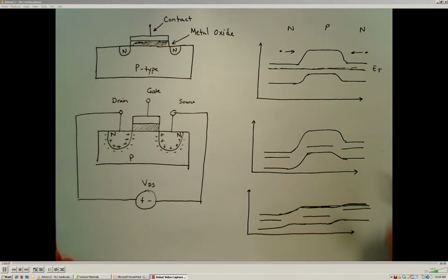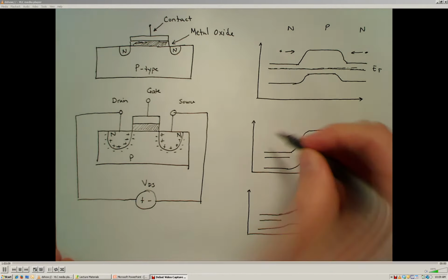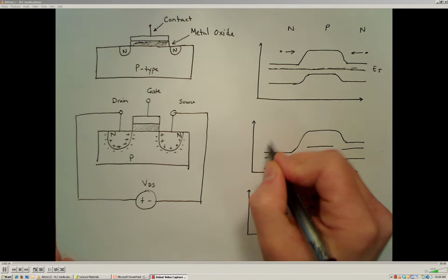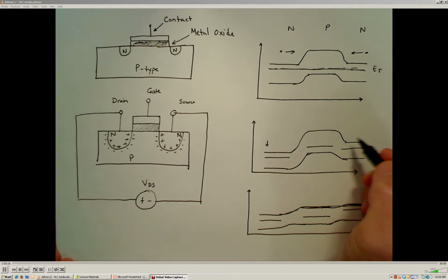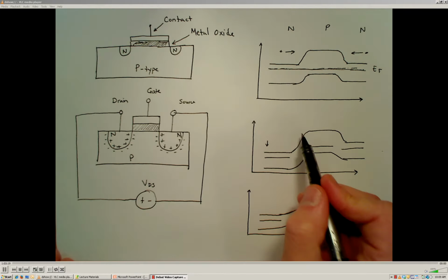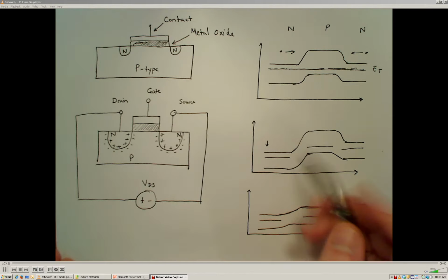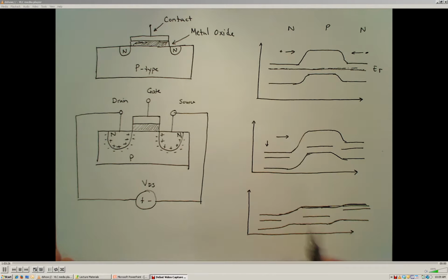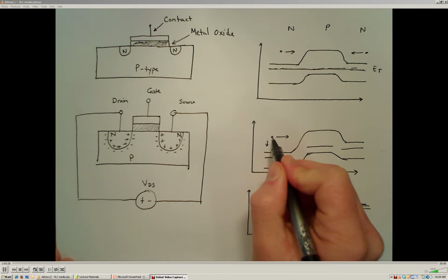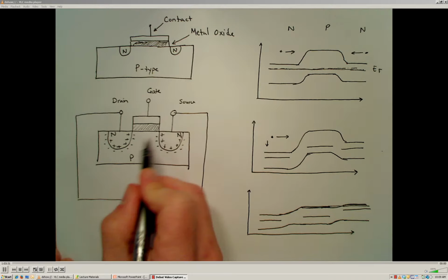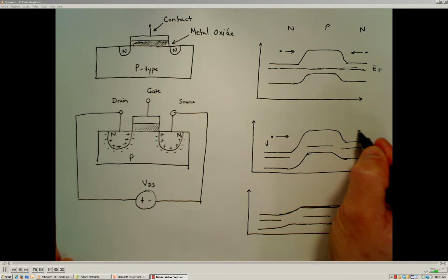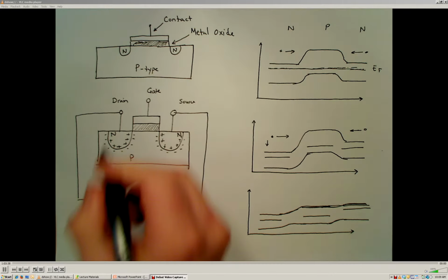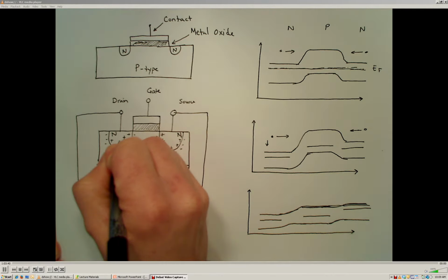Alright, so when we apply a positive potential difference, our Fermi energy level is going to shift downward in this direction. And we see that by doing this, we're going to increase the potential energy barrier to charge transport in this direction. So electrons will certainly not be able to overcome the barrier here, and we do very little to change the barrier in this direction. But what does happen, since we're adding more positive charges on this drain well right here,